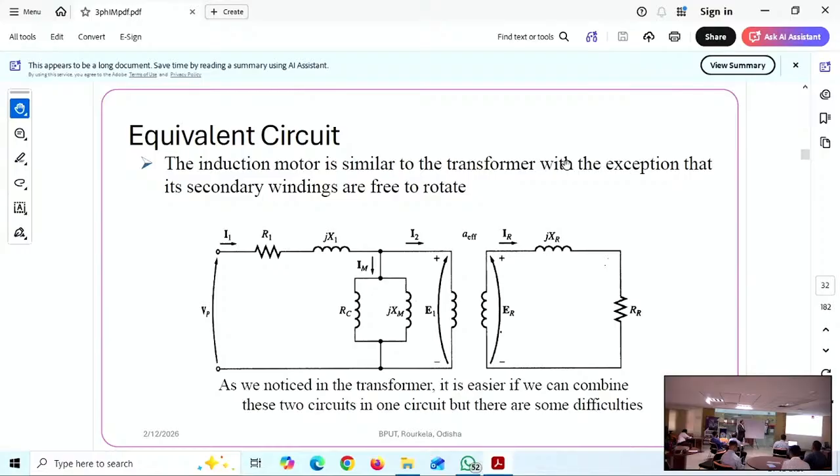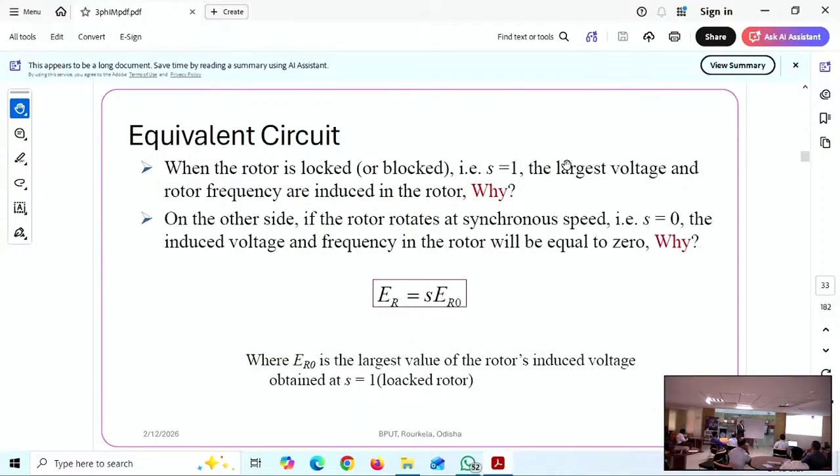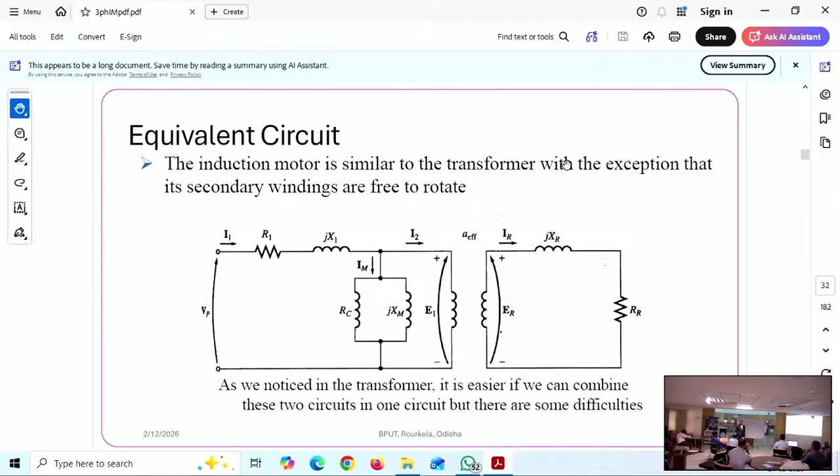In an alternator, this XM that I mentioned is the armature reaction reactance. That part is for the armature reaction. Then this is the leakage reactance of the stator. Combined, they give the synchronous reactance. Then this armature reaction reactance part is called the fictitious reactance. Okay, that part is there.